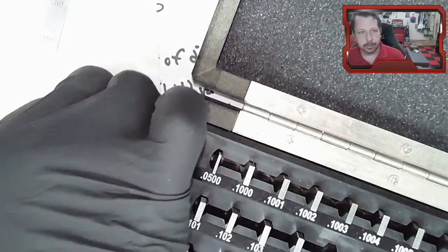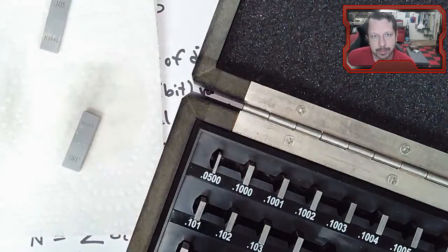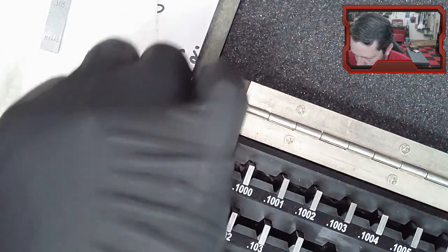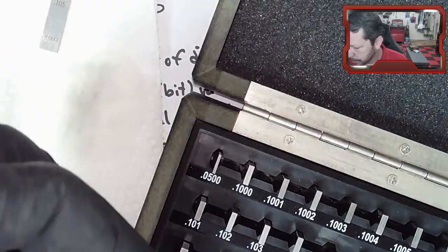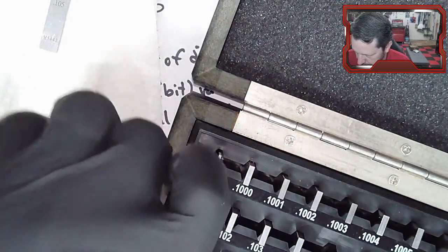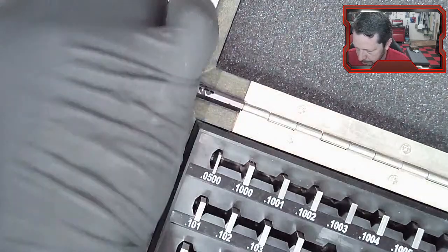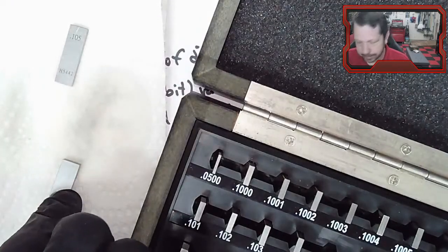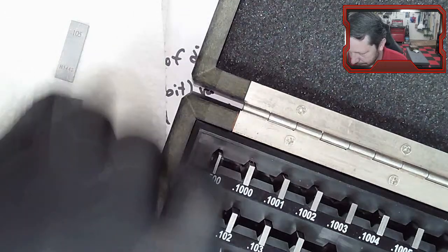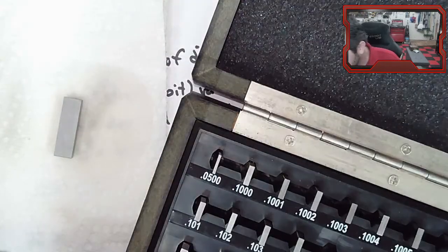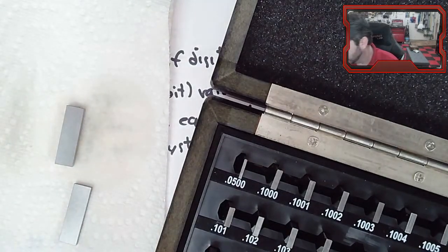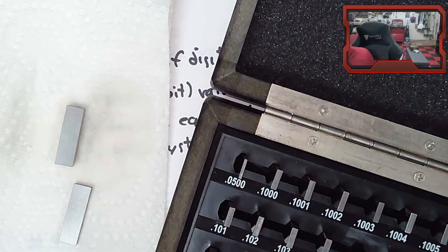Sometimes you take a stone, like a whetstone type thing for sharpening a knife, but it has to be super flat, and you can run them across that to make sure there's no burrs on them. These I haven't used very much, so they shouldn't have any kind of burrs. You don't want to wring a block if it's got a dent or a spot that's poking out. You don't want to wring that with another one. So there's a couple of different ways to wring. And again, these won't wring super well because they're pretty cheap compared to normal gauge blocks.